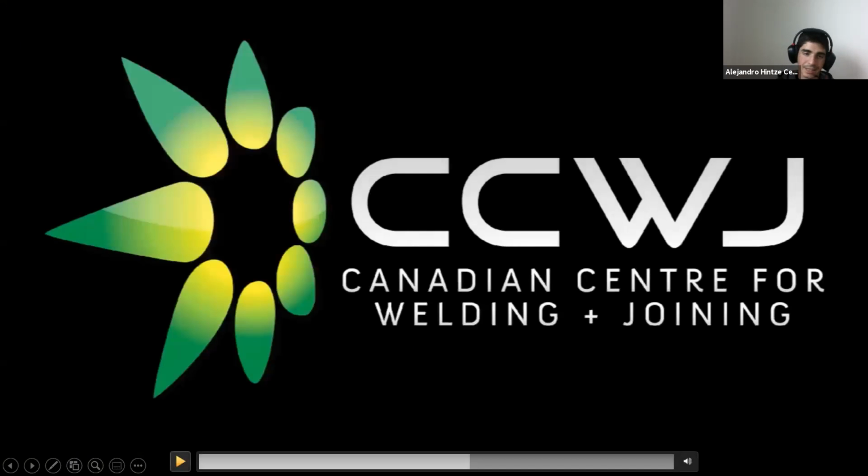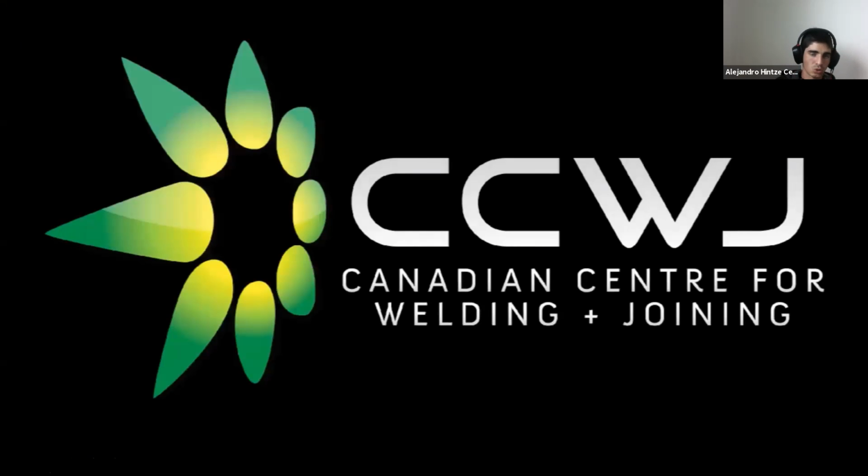So you'll see that between the last two, the arc looks different, it sounds different, and we can go back again, but we can see there is almost no sputter. Like you can see sputter going around before, and again, this is another transfer mode that has a high efficiency electrode, because all the electrode is spraying into the puddle, right?